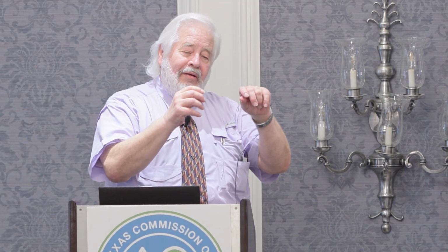I'm going to run that filter for X, I don't care what my head loss is, I don't care what my turbidity is, I don't want that filter running for that long because there's an increased risk that I'm actually going to cement a particle to my filter media. Or I'm going to grow a biomass in my filter that I don't want in my filter, okay? So I'm going to clean it whether I need to clean it or not.